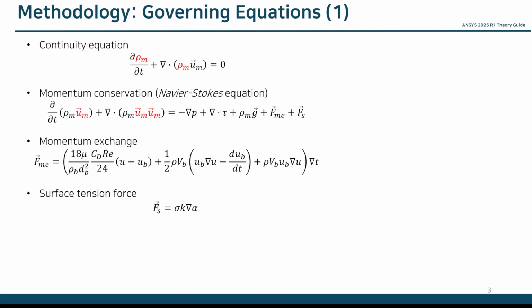In the simplified model, two species in each liquid and gas phases are allotted in the system. Therefore, two species transport equations are computed in total to obtain their mass fraction values because the n-1 number of species transport equation in each phase is only required, and the other mass fraction can be obtained by subtracting the sum of the mass fractions from the unity.